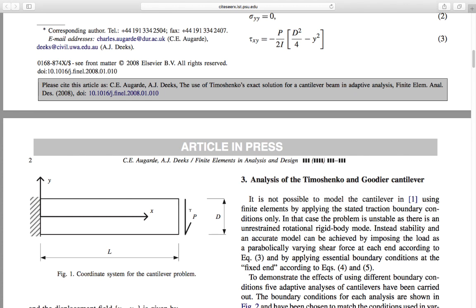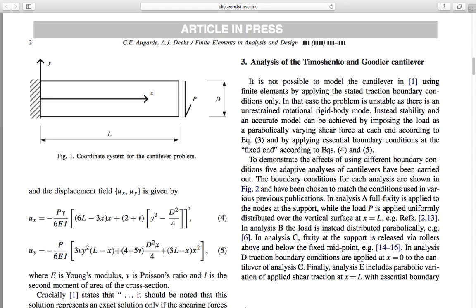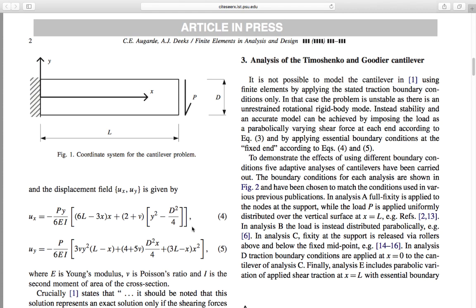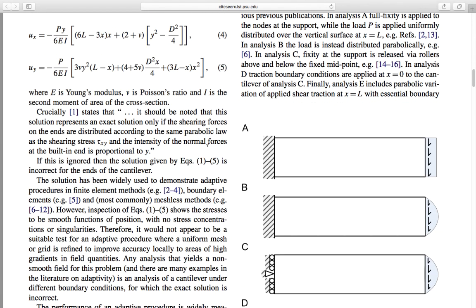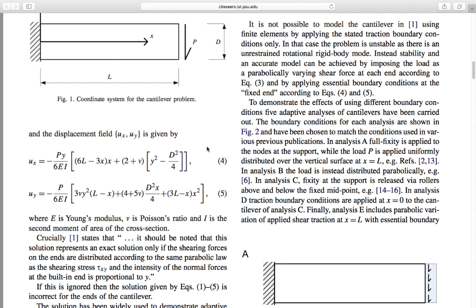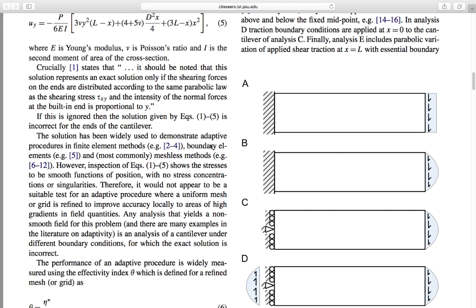I will give you a couple of examples later when we start working out this problem, but you can see that the displacement in x and y is much more elaborate for both the directions than just the one that we just saw analytically for a pure bending beam. So therefore there are some terms that are additional to this which are attached to this problem. You can also look at other sources to get simpler equations just in one dimension. You don't have to pick everything, but it is possible to get the shear term included in it, which gives you a better analysis result or some finite element approximation actually to start with.